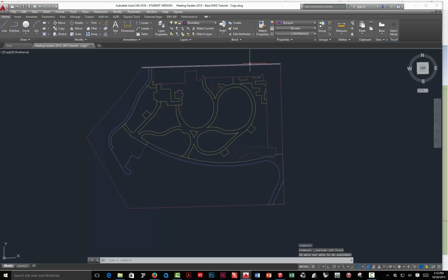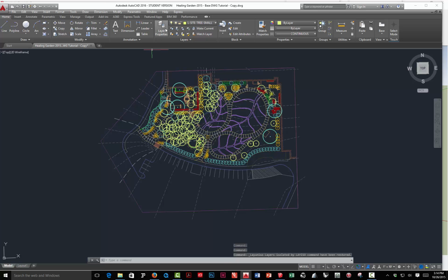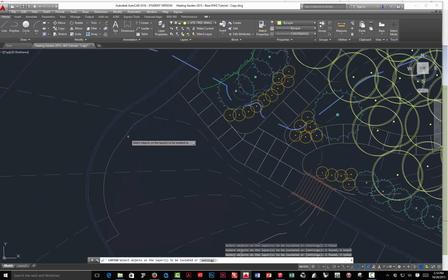I lost my polylines here. That's all right, because in SketchUp, polylines don't exist. They're just lines. But what I have now is arcs instead of arcs within polylines, and that's what I want. So now I'm going to back out, click on Layer Unisolate, and go through that process again. So this time I'm going to select the topo as well.